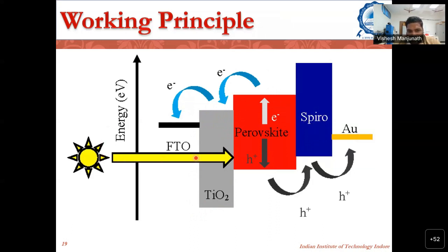So as soon as the light enters, the electron hole pair generated in the perovskite layer actually dissociates, because the electron sees the lower energy of the TiO2's conduction band. And we have to also know that the dissociation energy for this electron hole pair in perovskites is pretty low. So there is no need of any additional energy, and that's the reason people make HTL free cells. You can either make a junction only with perovskite and spiro, or with perovskite and TiO2. The electron hole pair binding energy is very low in perovskites.